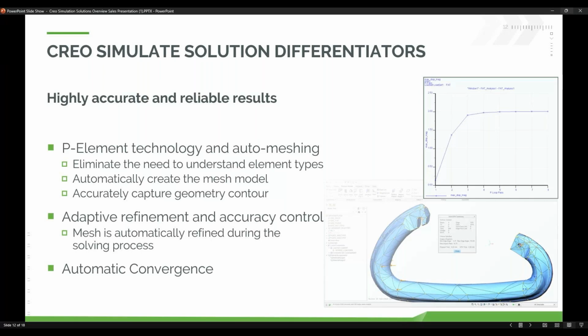And you have automatic convergence. There's 2 convergence methods within Simulate, and I'll mention them briefly when I do a static analysis here in just a few moments. You have a single pass adaptive. What it does is this is the polynomial order or the edge to an element order of 3, runs the analysis, runs through an algorithm, predicts what the polynomial order of each one of the edges should be, sets it to that, reruns the analysis. That gives you an automatic convergence.